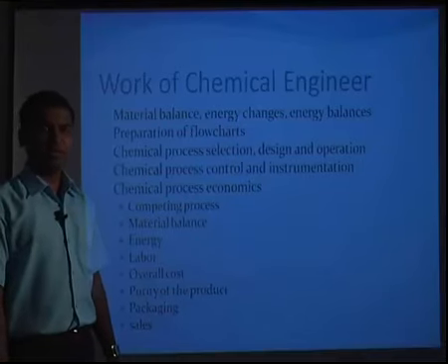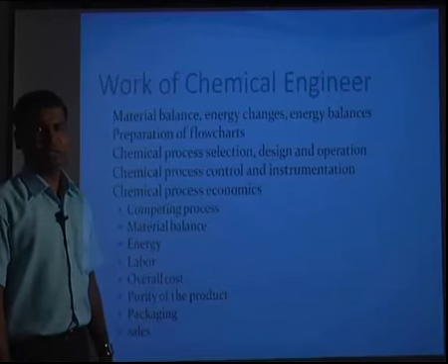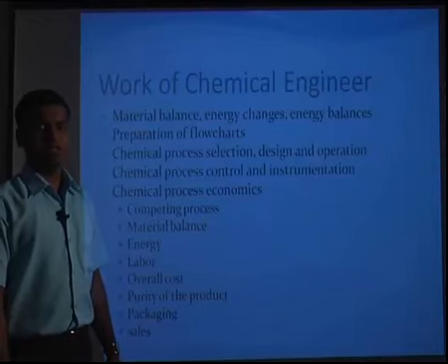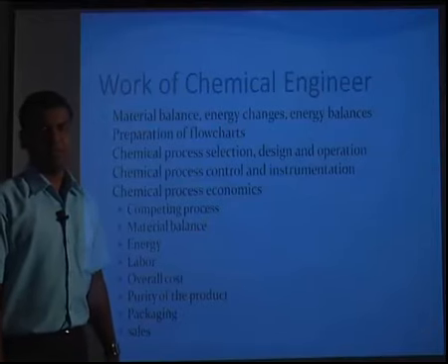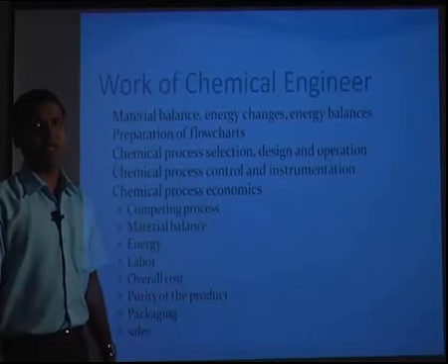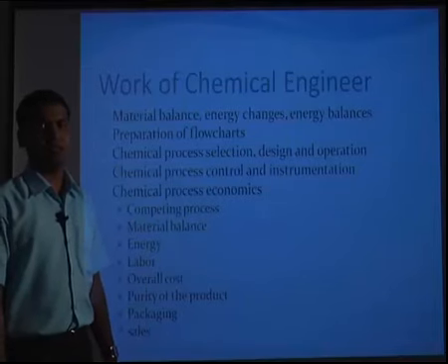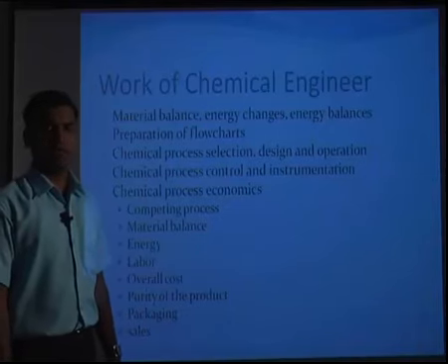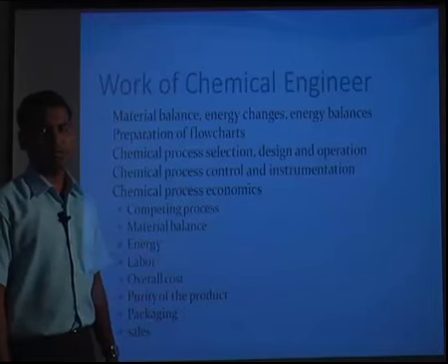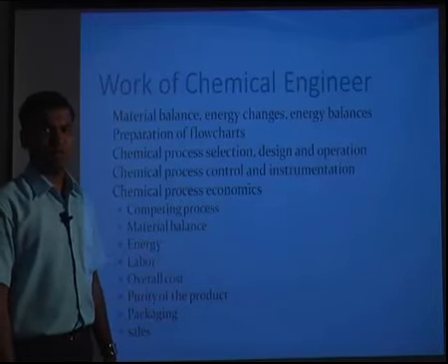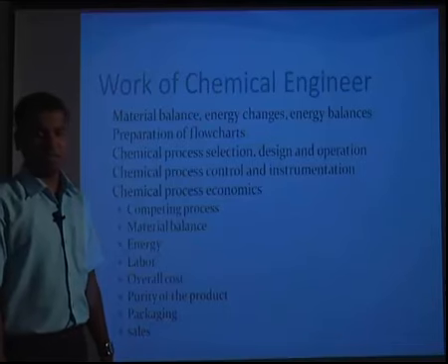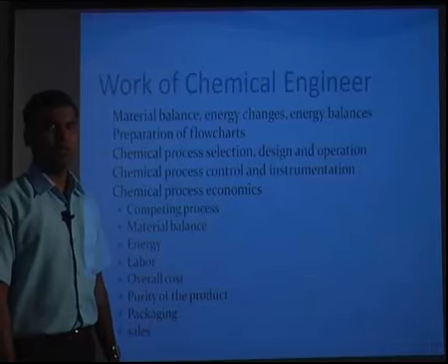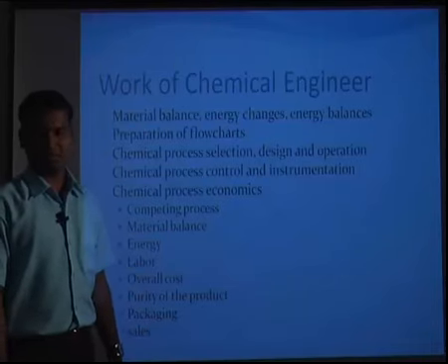So yield means how much the input is converted into the output, whereas conversion specifically deals with how much conversion is taking place from the input. If the conversion is not sufficient, we have to recycle them again and again in order to get the maximum conversion. Yield may be 80%, but conversion may be 10%. In this case, we have to recycle it again and again, which adds up to cost. So we have to look for the process, and we have to design the parameters such that the yield should be equal to the conversion, and that is the most efficient and most economical process.